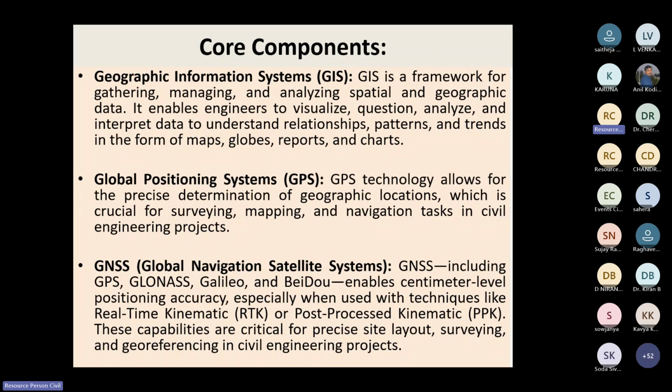If you use a GNSS instrument, it is directly a geodetic survey. That means the surveyed maps consider the earth's curvature in the output. But with total station and these instruments, when you draw or prepare any map, we are not considering earth curvature on our maps. If you consider a GNSS survey, it directly goes to the geodetic survey.